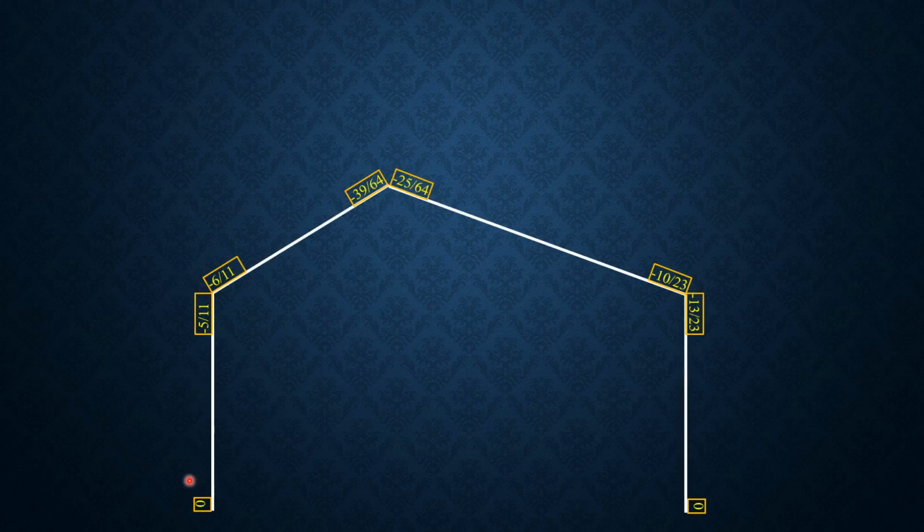So let's now have the distribution of the sidesway moments due to delta 4. Remember for AD, this is 0, so we'll just put none at all. Then here, it's negative 46.286. Then here, positive 16.483. Then here, negative 30. So the distributed moment here is 0, 0. So this is also 0.